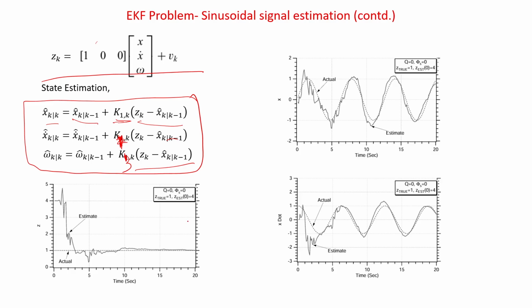So, you get now your true versus estimate. You see now it is kind of a pattern, at least it is holding the pattern. Although tracking I won't say is very good, at least it is holding the pattern. This is your estimated, this dash-dotted line is your actual true, and this is your frequency, the constant frequency whichever you are having. So, that is your actual Z. But you can still better it.